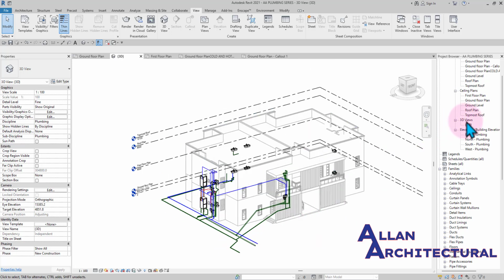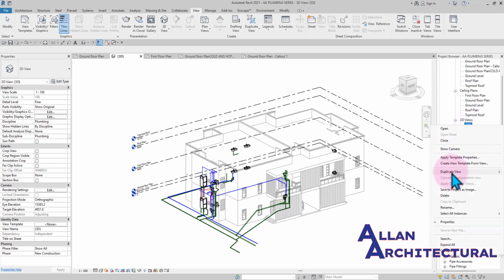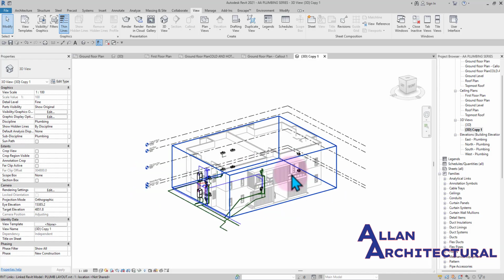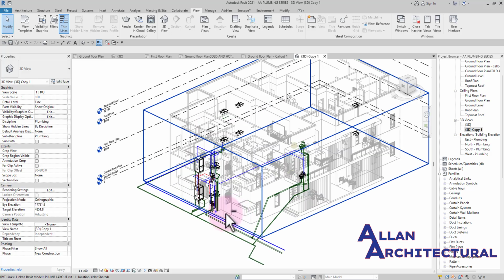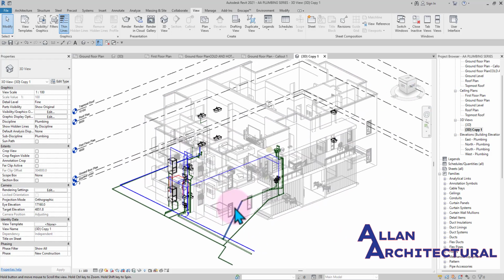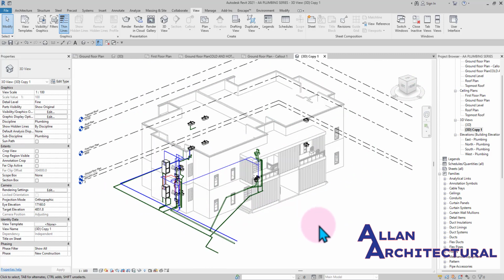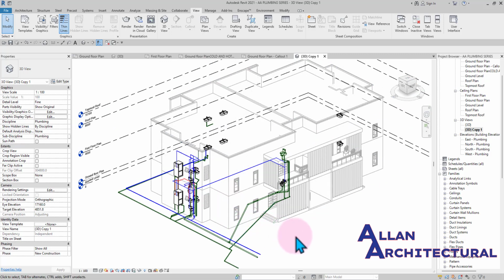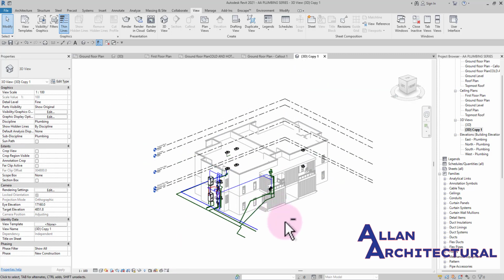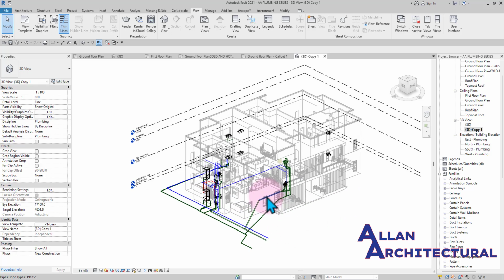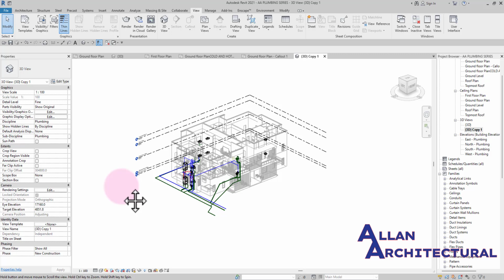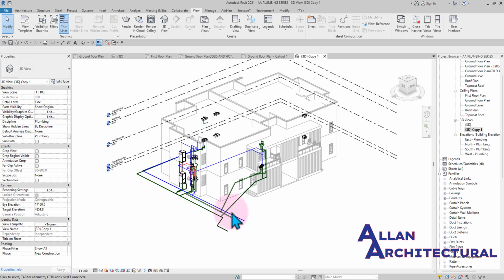So when it comes to the 3D view, you would also want to duplicate that view. All right, so we can duplicate that view, and then we have this view here. You might want to pan around, just orbit around to the view that you'd want to bring out, or maybe you would want to bring out the entire building. All right, it's also acceptable. You can bring out the entire building, but let's say I want to bring it this way. So what I can do now is make sure I lock this 3D view. You notice we have this building here, and then you can lock and save the orientation lock view. So when you hold the space key and try to orbit, you are not going to be allowed to orbit. You can just pan around a little bit, but you cannot orbit around the building.